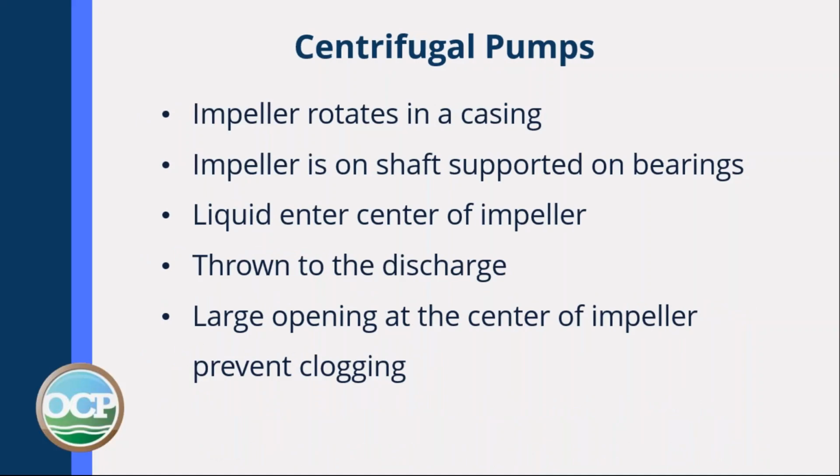Centrifugal pumps are the pumps that are used mostly in the water and wastewater industry. It consists of an impeller rotating in a case. The impeller is on a shaft supported by bearings. Liquid enters the center of the impeller and it's thrown to the discharge by the speed it picks up through the impeller. And typically these pumps have a large opening at the center of the impeller to prevent clogging, even though we all know what the disposable wipes do to them, don't we?